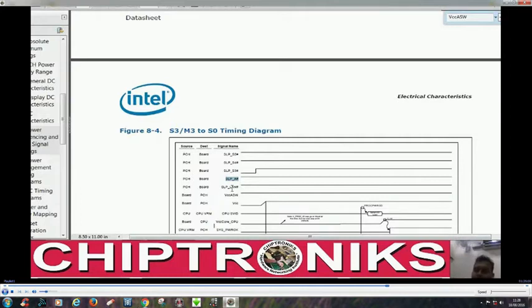So you can see the IO controller and PCH work together to control the power sequence. Some part of the function of the PCH is done by the IO controller during power on. So the IO controller and PCH both are important in turning on the laptop motherboard.